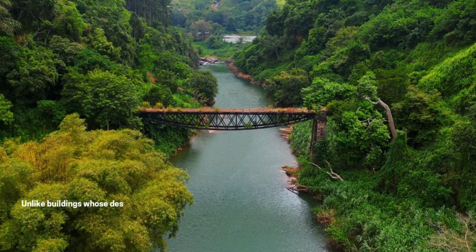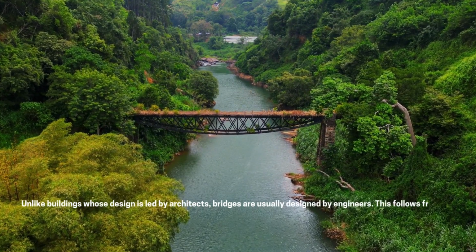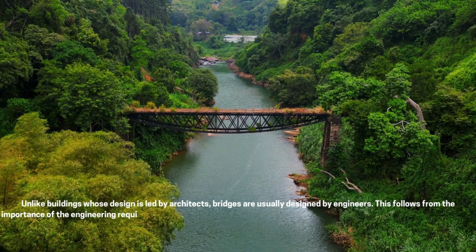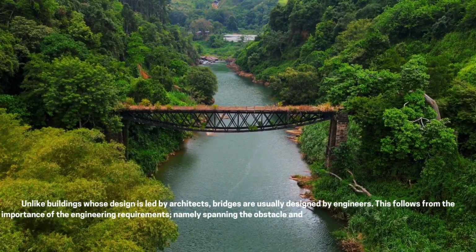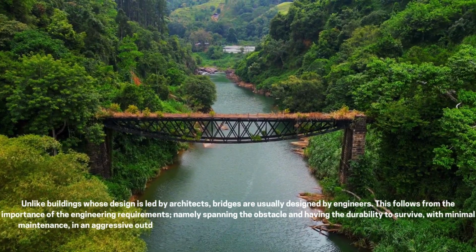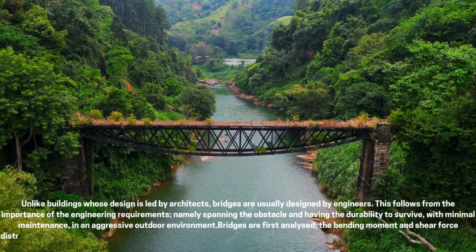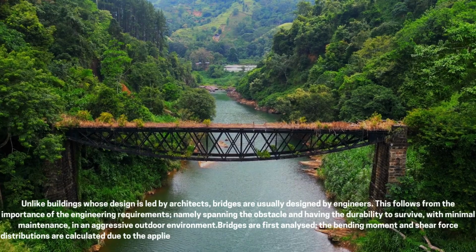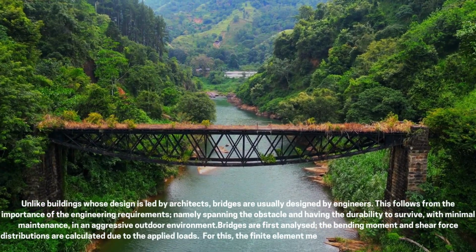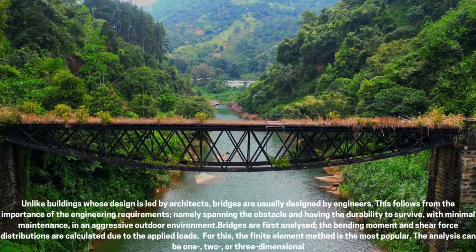Unlike buildings whose design is led by architects, bridges are usually designed by engineers. This follows from the importance of the engineering requirements, namely spanning the obstacle and having the durability to survive, with minimum maintenance. In an aggressive outdoor environment, bridges are first analyzed. The bending moment and shear force distributions are calculated due to the applied loads. For this, the finite element method is the most popular.